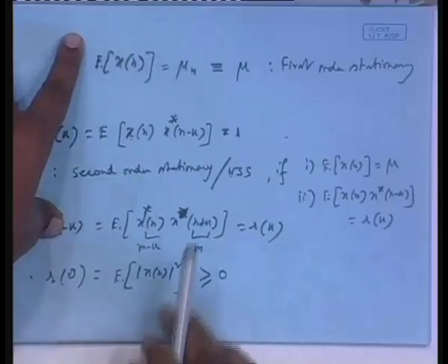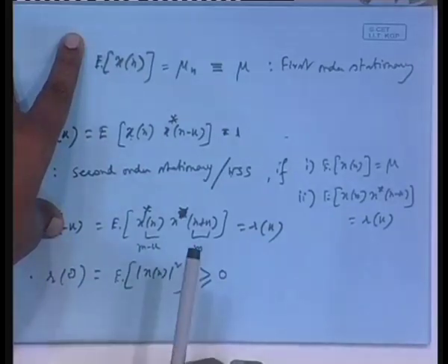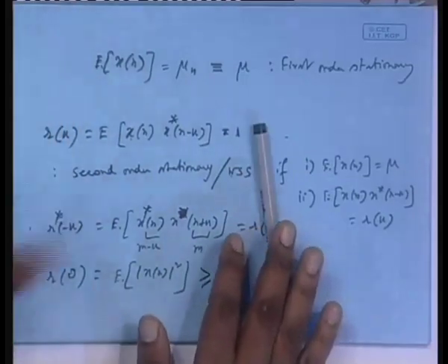Why are you calling this power, R0, an expectation? Because that is the ensemble average. Power is something related to time, right? No. Power actually, for a random thing, I should only have this. The time thing is a follow up. A random variable is given. I will look at the sample purely as a random variable located at the nth point. Because of the stationarity assumption, you get the same value whether it is n or m or l or k, but this value is changing from time to time. This observation has one value, the next observation a high value. So it is changing. So what is the average power of that particular sample?